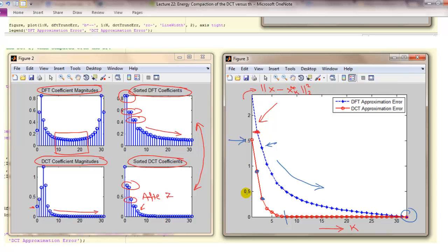And what would end up happening is that an image, which will probably have, let's say 10 million pixels, which is effectively, if you talk about grayscale, 10 million numbers, you can store them by perhaps using only 2 million numbers. That's a compression by a factor of 5. So discrete cosine transform is really good in terms of capturing energy in smooth signals, signals that are slowly varying.